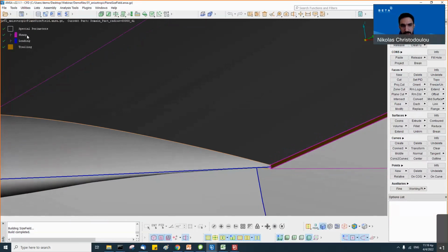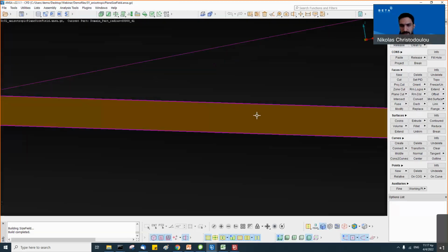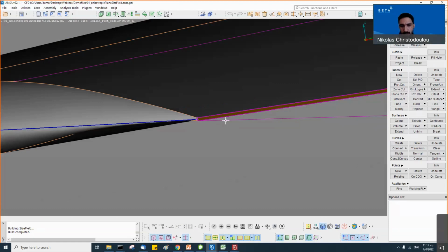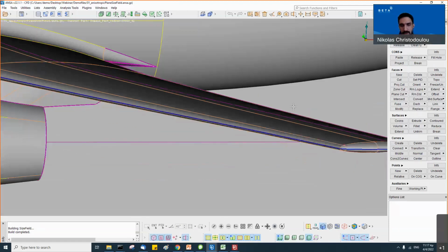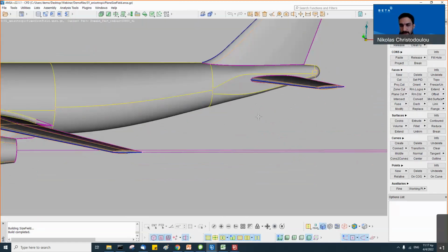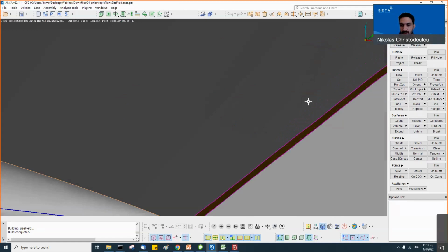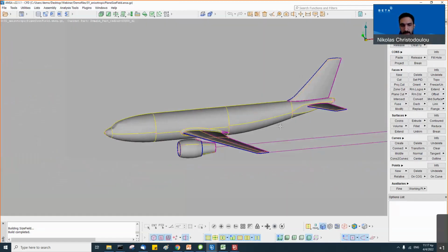On the top left, you can see the legend. So here the trailing edges are brown, some sharp edges are colored pink, and you can see in blue the leading edges. So these are automatically identified by ANSA. And then, based on the recognition, specific mesh treatments can be applied.